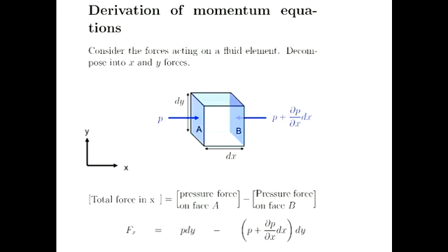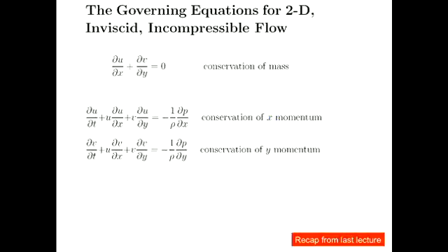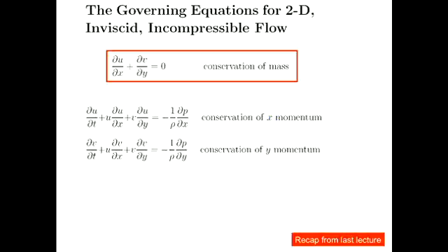The only tricky term in there is the force term, which is just due to the pressure gradient acting across that control volume of fluid. If you set that problem up correctly, it's very simple to nut out, in this case, that x component Euler's equation. You've just got a force due to pressure, and then mass times acceleration. We showed that the acceleration in the x direction is just the total derivative of that streamwise velocity component u. And so you can very simply get to those 2 expressions shown at the bottom here.